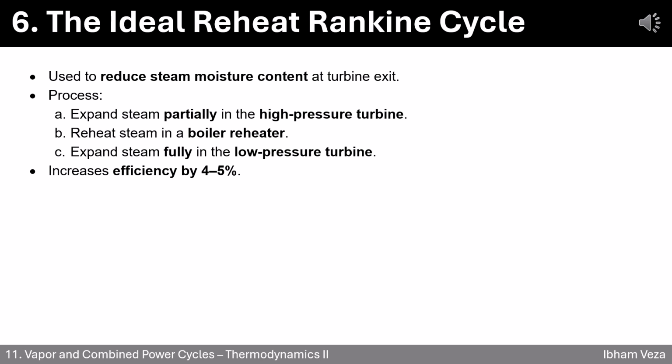This small modification of adding a reheater increases efficiency by around 4 to 5%. It's a smart way to get more work out of the same fuel while also making sure the steam stays dry enough to prevent turbine damage.